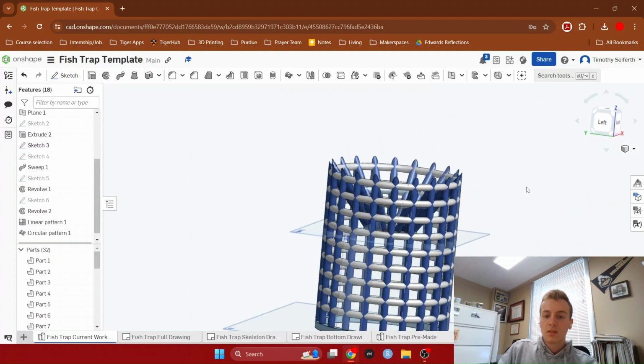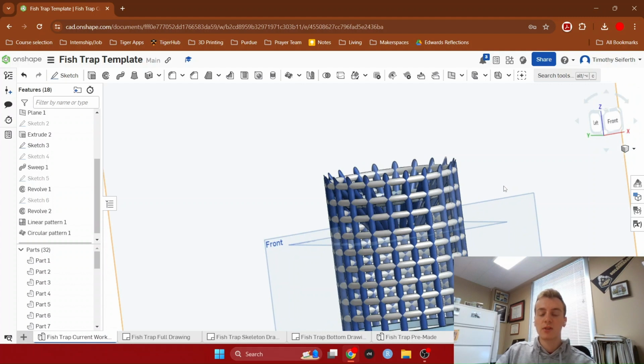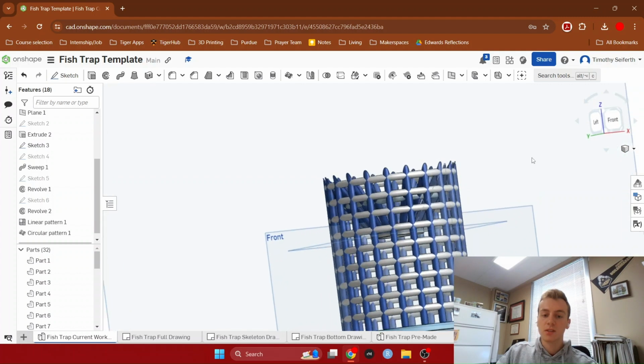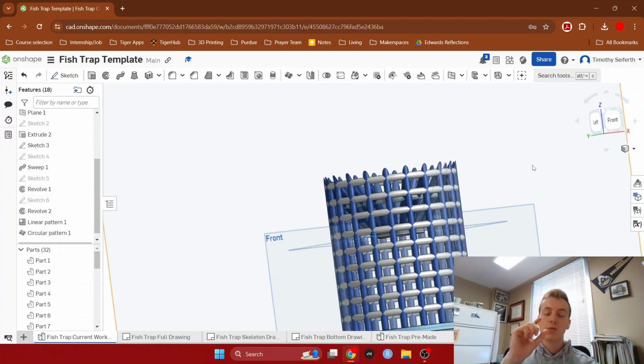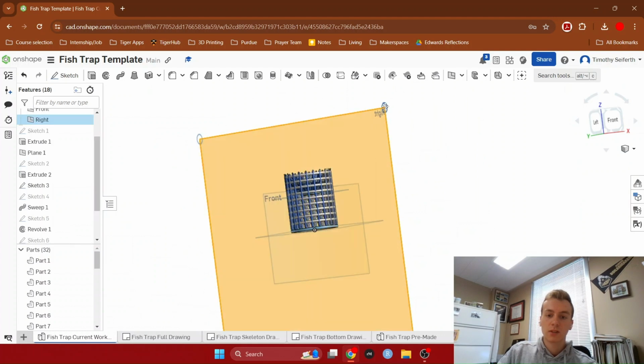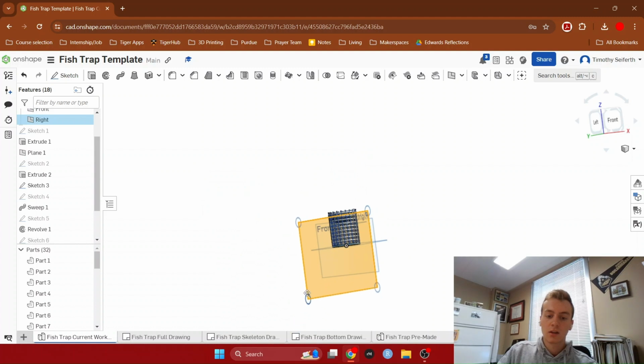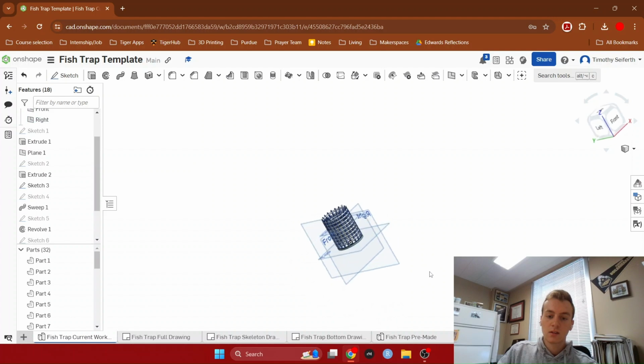Now, this part is not super necessary, but just for ease of 3D printing and for better shape, we're going to take off all these little points at the top, which is really easy. It's just a removing extrude instead of an adding extrude. So we're going to make a shape that then takes away parts. I'm going to shorten this guy down a little bit. He's a little too big, actually. There we go.